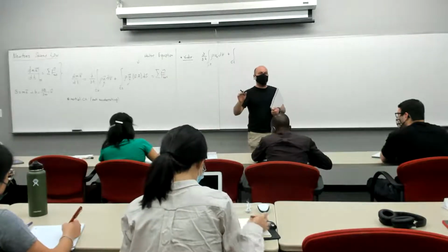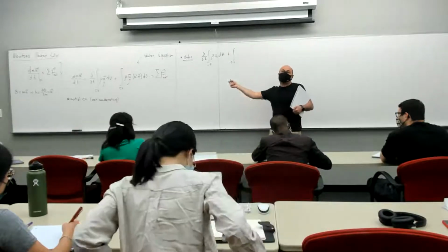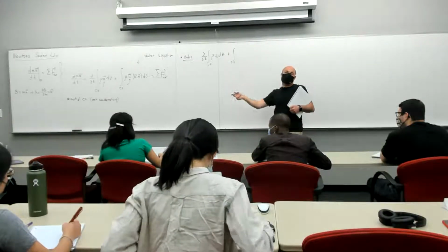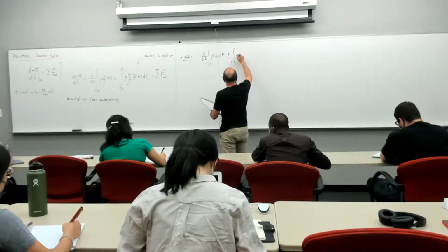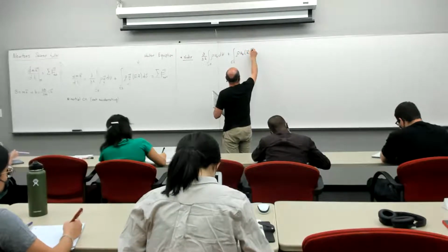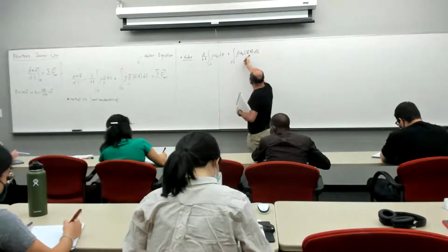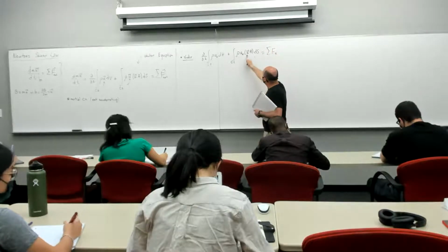The intensive property could be anything, could be phi. In this case, it just happens to be the velocity, and we're taking the x component of that velocity. So this would be rho ux u dot n dS, equals the summation of forces in the x direction.